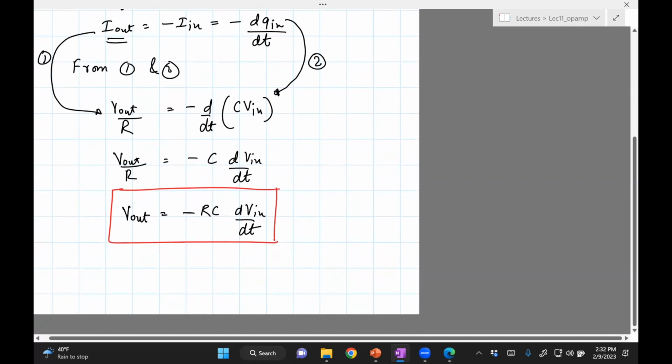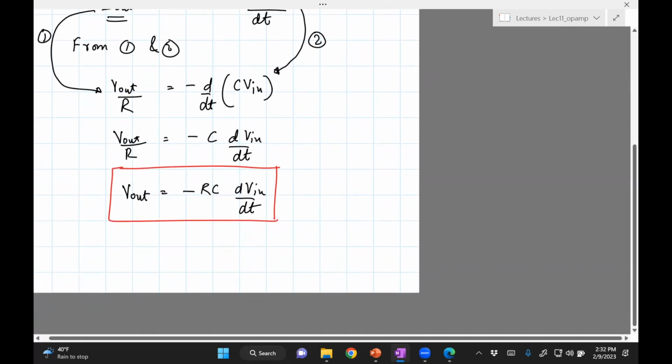So where could this be used? Well, if your input is, let's say, a sensor which gives you position, then your output is going to be the derivative of the position. So it will give you the velocity. This is a way in which you can use an operational amplifier to do computations by itself. You don't really have to write any code, right? There's no code here. There's just this Opamp machinery, which gives you the right output depending on how you wire it up.